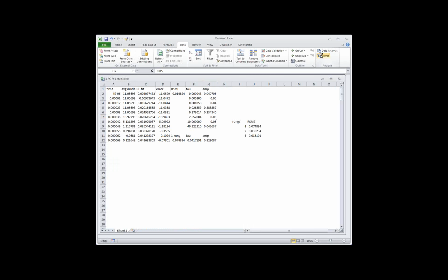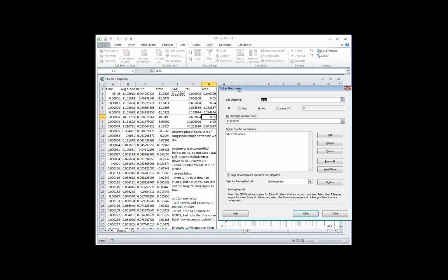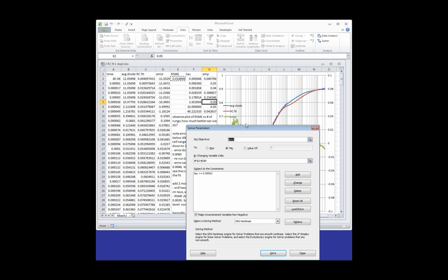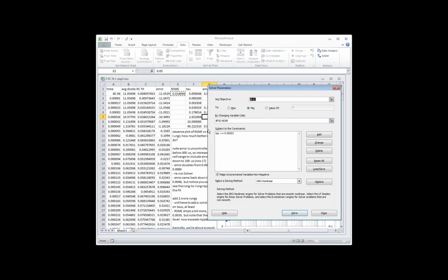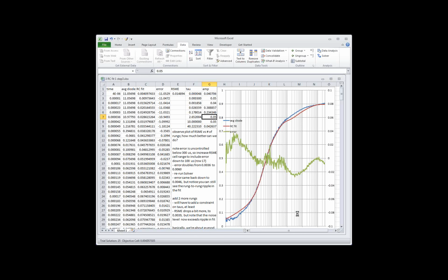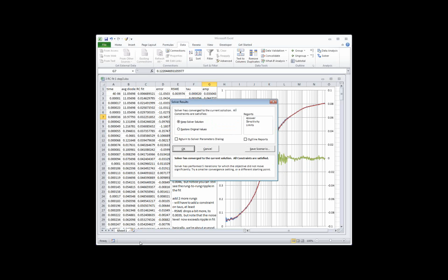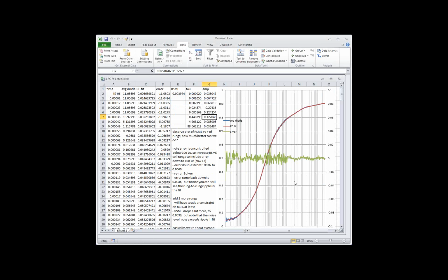Pick the solver again. Notice the solver has, again, adjusted. It already knows that we need to go all the way down to row 9, remembering the constraints. Oh, it even renamed the constraint to apply to tau. That's interesting. So let's say solve. That took long enough that if you were looking at the lower left corner, you might have actually seen something. Well, now look at what that fit is like. With an 8-run model, we got our error down all the way to 0.0039.